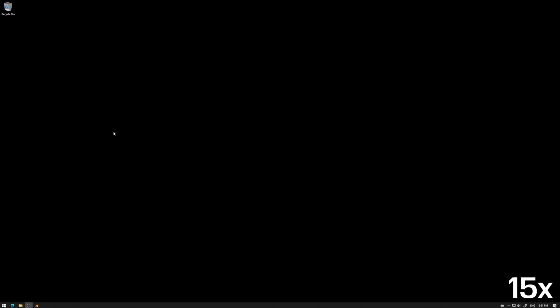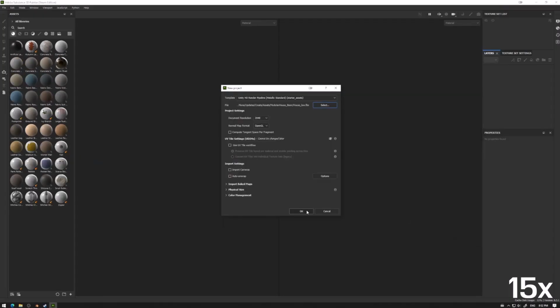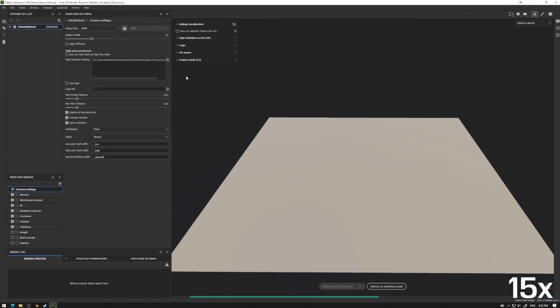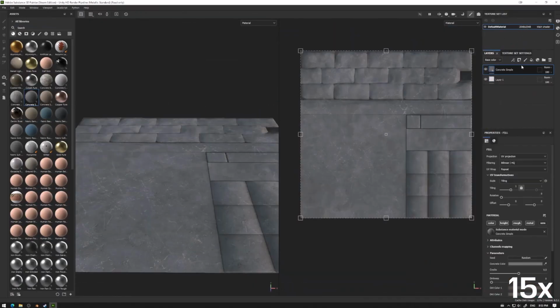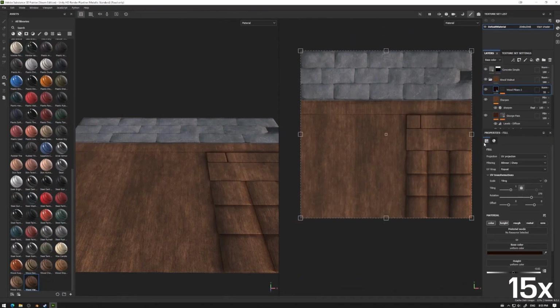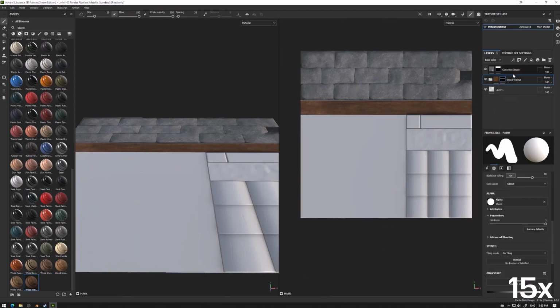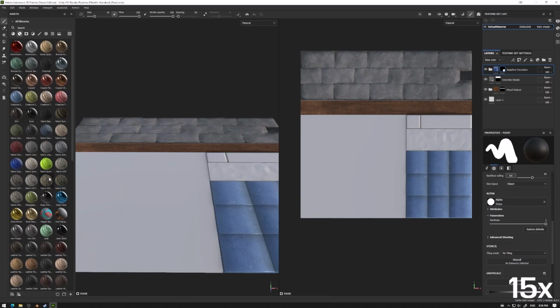The next stage is taking the high poly assets into Substance Painter to bake them onto a simple polygon square that results in the texture to be used on our final assets. I can then add some color and add texture using Painter's materials to bring some life to the end result. All of this is in order to make the texture, or the material. This has nothing to do with the modular assets that I create with this trim sheet texture in mind.